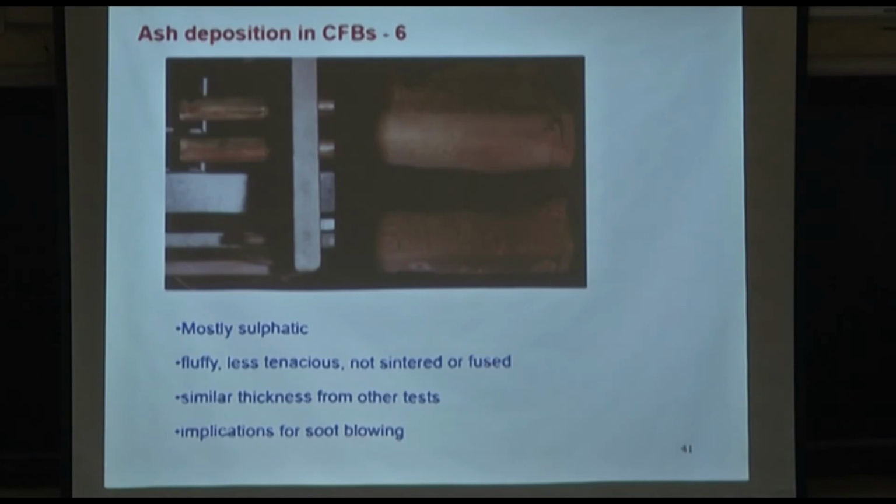The air-cooled probe was kept at 600. The first batch was at 600, the second batch was 550, the third batch was 500. So that's how we were managing it. Exactly what happens in the economizer section of a power station boiler, progressively lower and lower temperature.